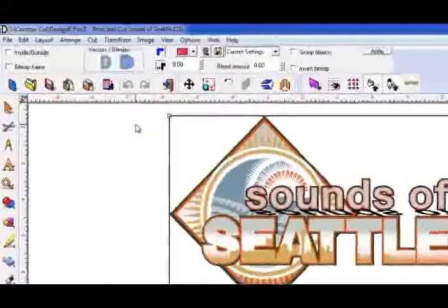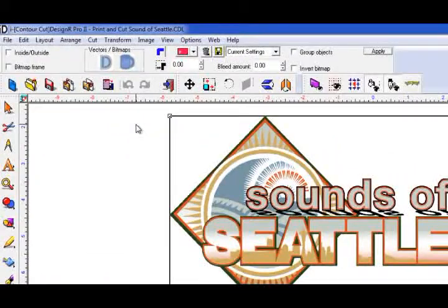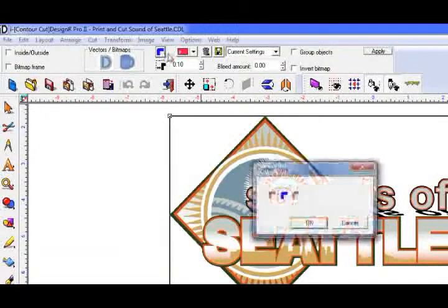In the Smart Bar are a couple of settings that we should go over. The Bitmap Frame checkbox will place the cut path around the rectangular shape of the image or bitmap, as if framing it. But this is not what we want. What we want is to contour the image here. This means that the software has to ignore the outside white space. Let's set the offset to 0.1 again, and set the cornering to sharp.